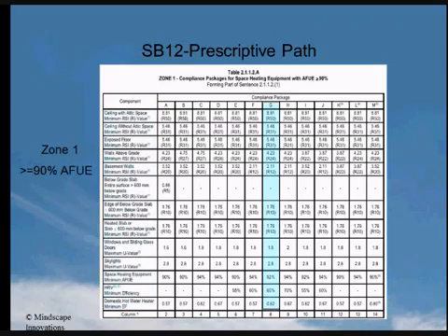Arbitrarily having chosen package G, we can see what the requirements are for each item, keeping in mind that the only surfaces that are in contact with both external ambient air or ground and whose internal surface is heated need to be insulated, for example, exterior walls and ceilings. For the purposes of calculating R value, any reflective surfaces shall not be considered towards the total.